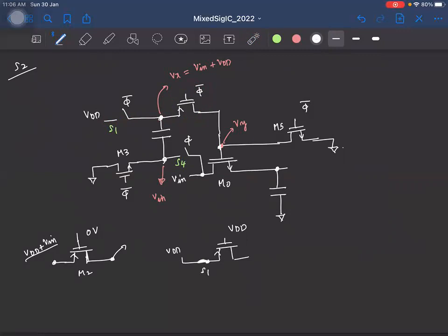Okay, and similarly, the other end of this switch S2, or this transistor M2, is getting connected to ground by the switch M5. So I'll have this connected to this. And since this is connected to VDD, the switch easily turns off. There are no issues. Okay, so let me just label this M2.